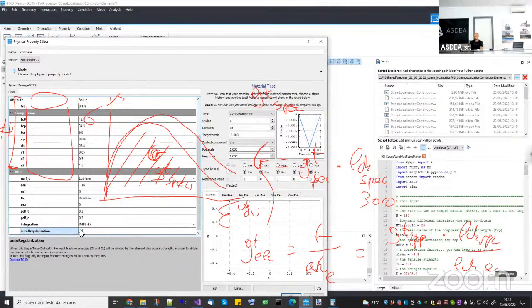Okay, so as you can see, I'm basically first deregularizing the initial fracture energy. So I'm going to the real fracture energy obtained from the experiment, and then I put it inside my model. Okay, and then with the automatic regularization, I will obtain a specific fracture energy correct for my element. Okay, I cannot input the initial one because the initial one is specific to the specimen.